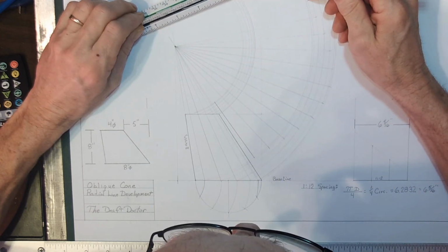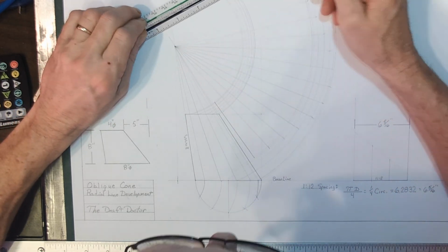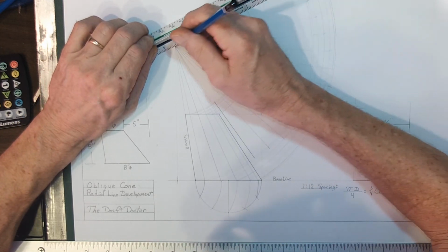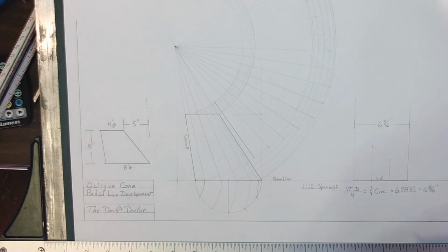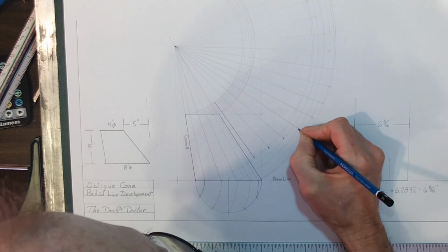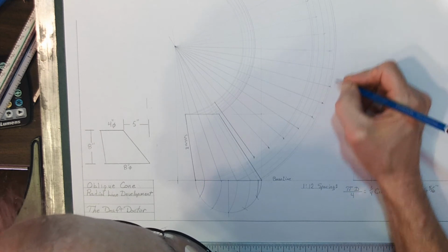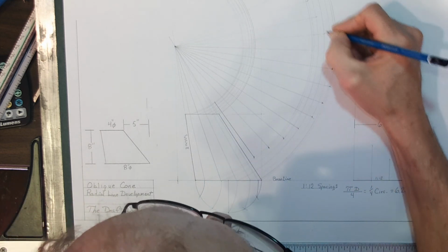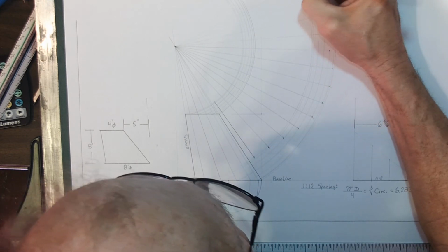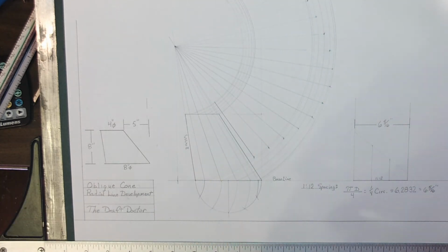There comes a point in our development as sheet metal tradesmen where layout is not as confusing as it once was, and it becomes a lot of fun, especially radial line. So here I have all my points, where they finish, on my 8-inch round end. And because I used my 1/12 spacing in between as I jumped across these radial lines, this is going to be the stretch out for my 8-inch round.